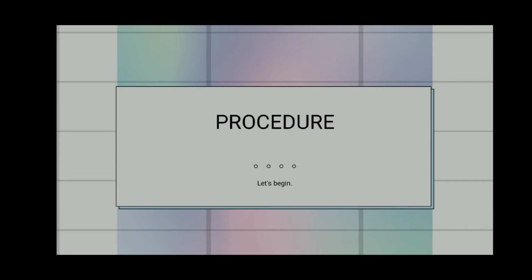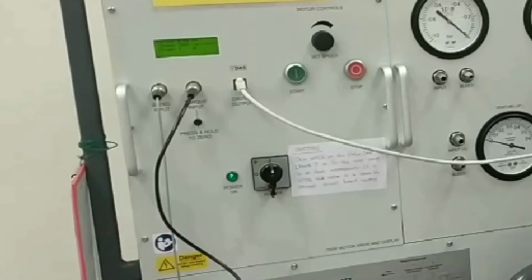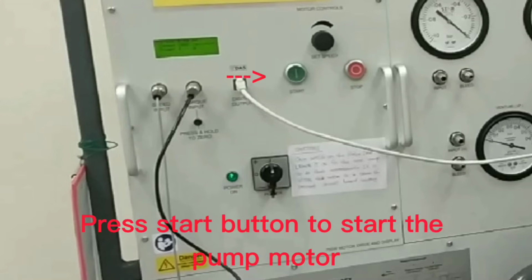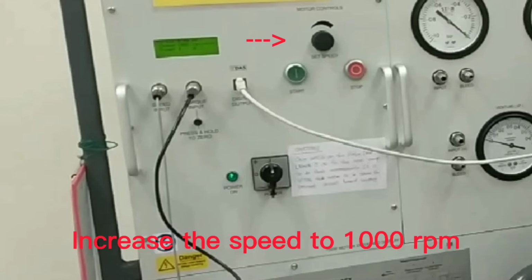Procedure. First, switch on the main switch and motor drive isolator. As a reminder, before operating the system, make sure the delivery valve is in fully open condition and the inlet valve is fully closed to make sure the pump is completely filled with water before running the system. Next, press the start button to start the pump motor. Then increase the speed to 1000 rpm.